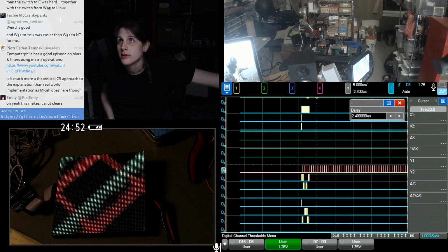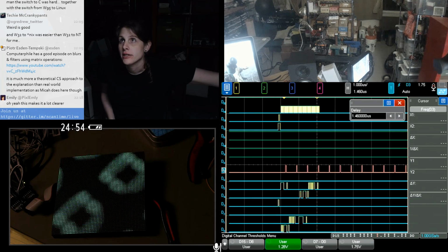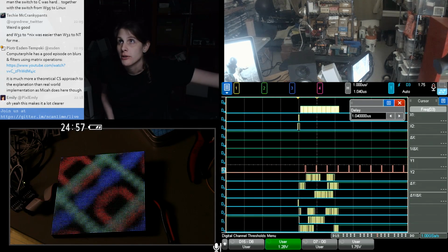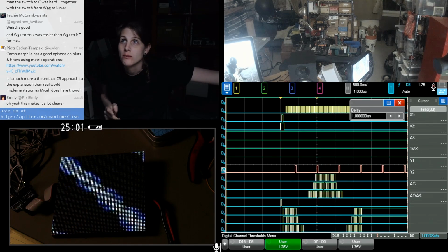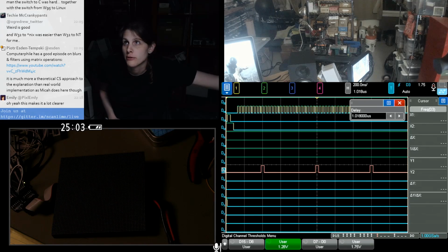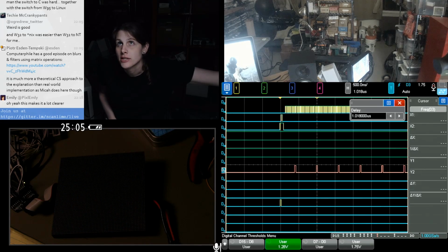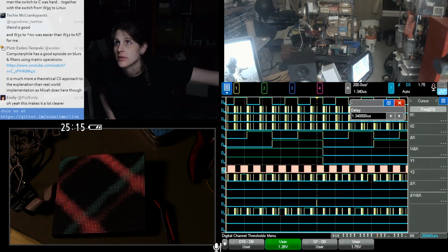And the data you're seeing at the bottom is actually a different row, not the one being rendered here, but the previous one that was rendered. It's that row being scanned out to the shift registers in the display, which actually happens a bunch of times per row. Yeah, no, 8 times, that's right.